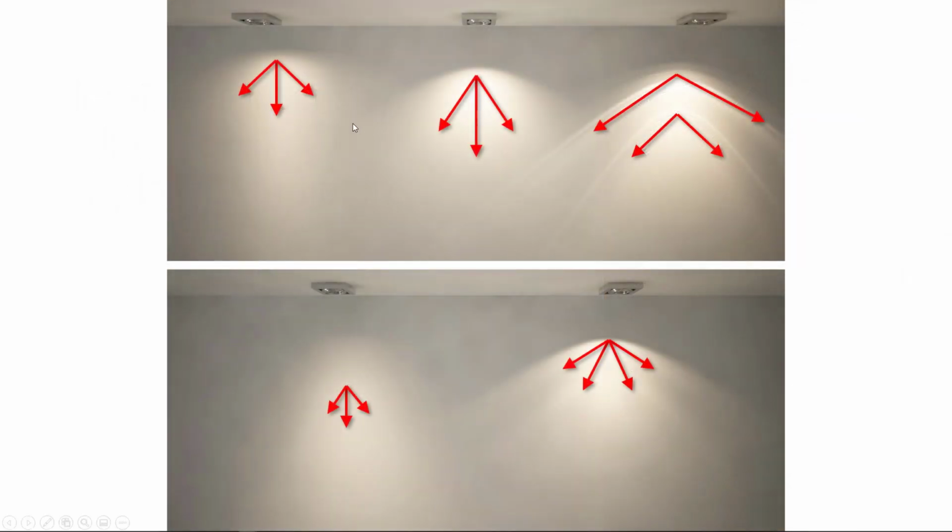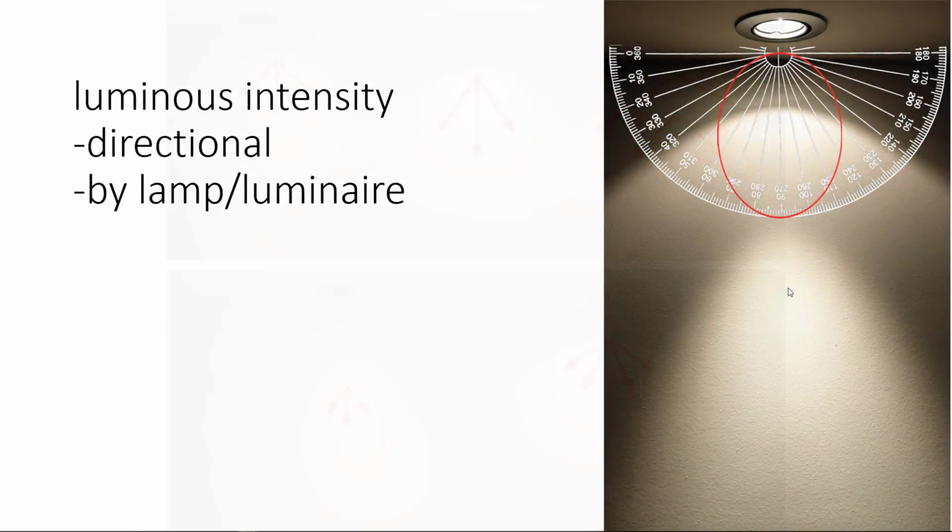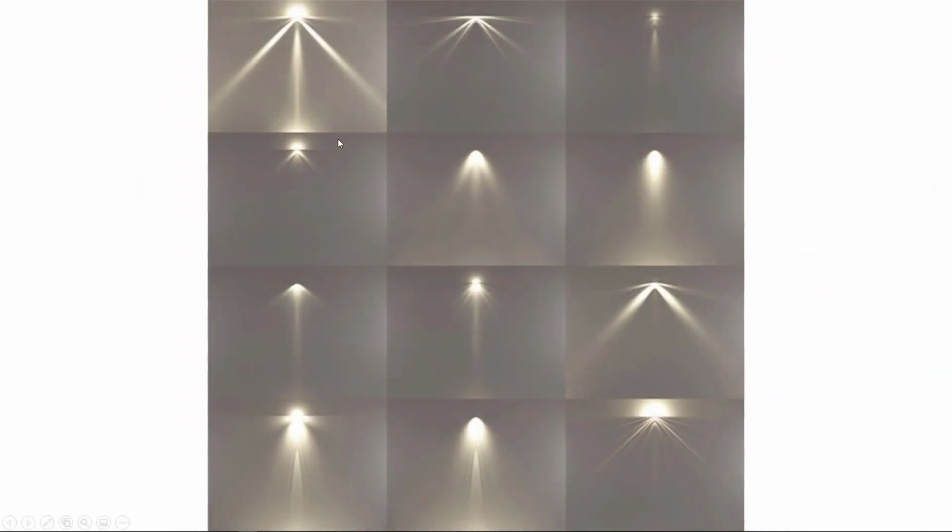What I'm talking about here is each luminaire, and these are very similar looking luminaires from Erco, a German company. Some have a light distribution that is quite soft and quite limited. It doesn't throw light very far. And as you can see, these patterns from each of these light sources are quite different. There's an infinite variety depending on what you're trying to do with the light. This light, for example, will throw a lot of light sideways, but basically nothing down. This one's throwing some light up. This one's throwing it in a much more soft kind of cone.